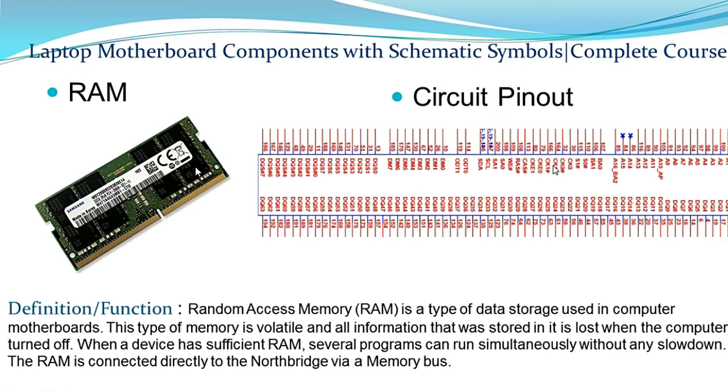And of course, the RAM doesn't have just one power. It needs 2 kinds of power. One main power and the VDD, or the power for terminals. The power for terminals is always half of the main voltage.